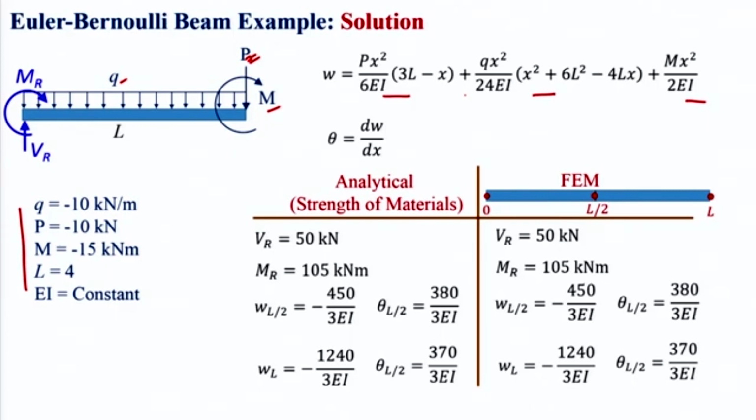and it is not surprising at all, because you see how we have computed the nodal degrees of freedom and reactions. We have used equations, and in those equations all the element level equations, element level matrices, element stiffness matrices, those matrices are exactly the same as the matrices that we have seen in the direct stiffness method or matrix method of structural analysis.